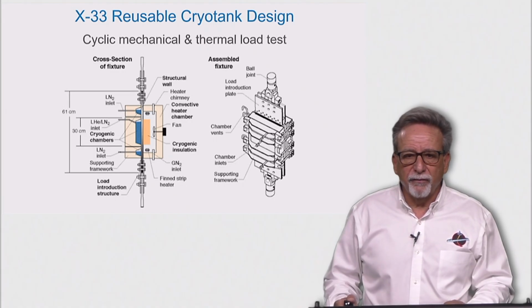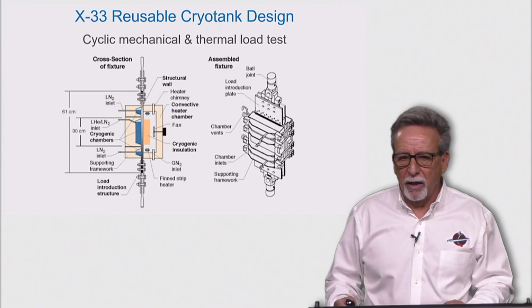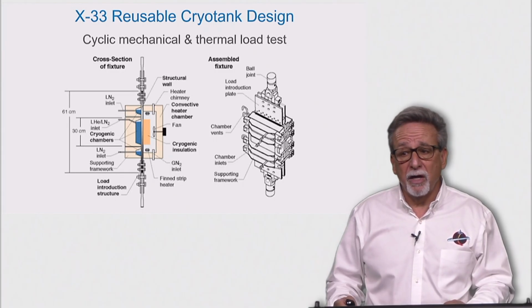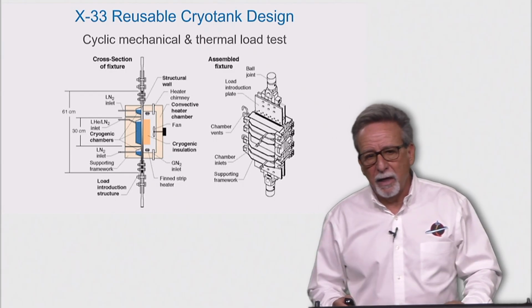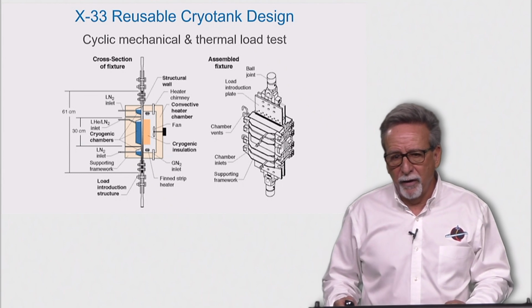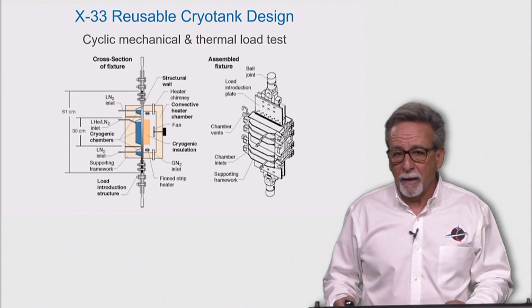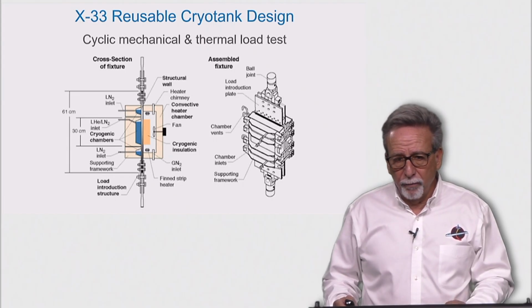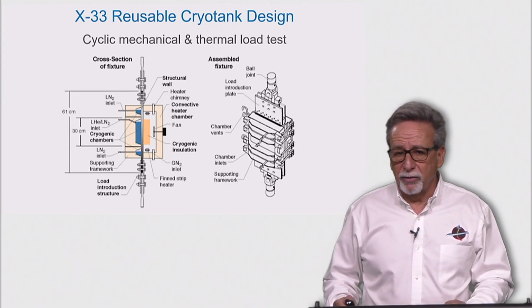Since the environment varies from extreme cold to warm, and the designs include brittle materials, it is also critical to match the actual environment and load conditions as closely as possible. Because as we say, the devil is in the details. And when materials are brittle and less forgiving, especially at cryogenic temperatures, very small imperfections or design details can lead to premature failure. In particular, thermal loads require a higher resolution finite element analysis to determine key stress concentrations.